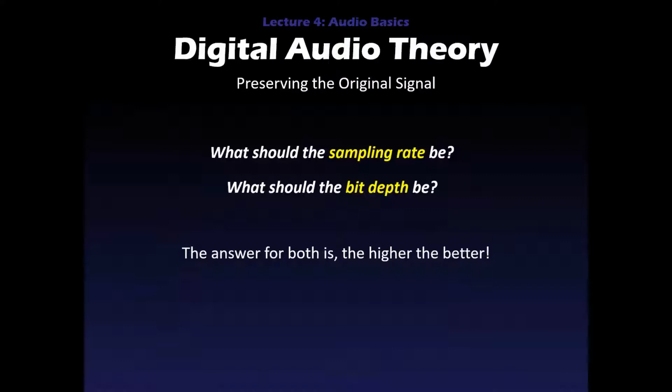It's kind of a measurement of, we're talking about quantization, how we store the samples. We need enough bits to be able to store these numeric values, the sampling rate. They work hand in hand. So the answer really is you want the most of each category. You want the highest sampling rate and the highest bit depth possible. And you'll see why in just a second.